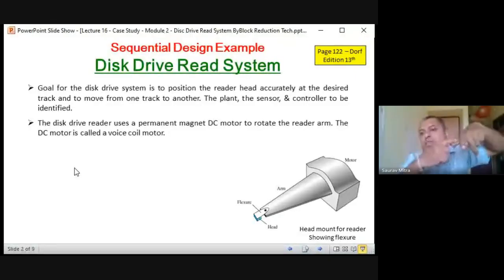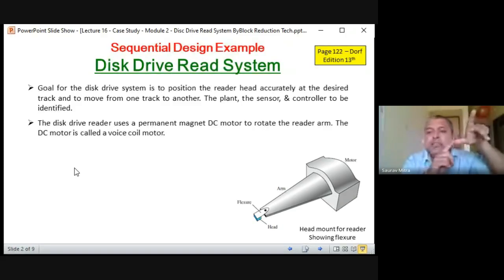So this is the direction of current. If these two are there, then there will be a force. There is the actual mechanical output. So two inputs: MMF, that is a flux input, second is the current input, and third there will be a mechanical force output. So this is actually the motor principle.